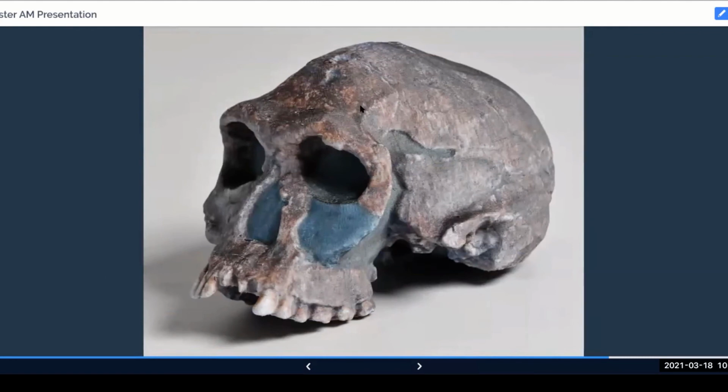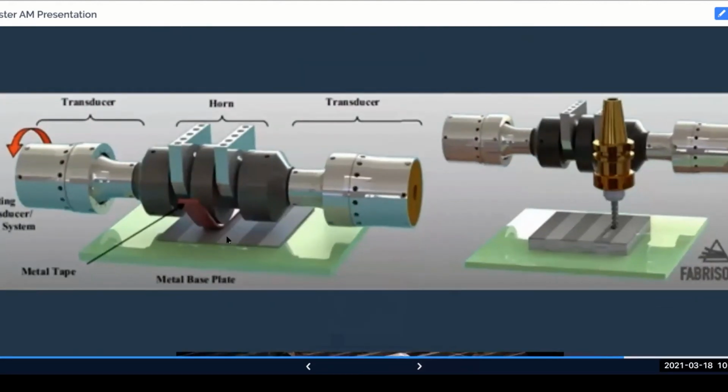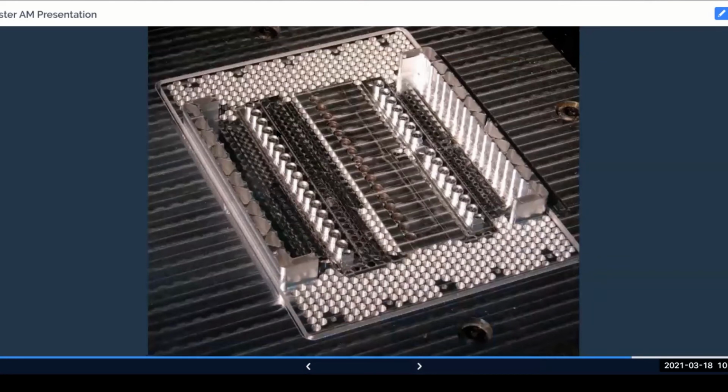So, in archaeology, they're doing this for reconstruction methods, things you want to put in a museum that looks good, like an original artifact, but isn't actually an original artifact. You can do that with this technology. So again, this is all 3D printed based on a 3D color scan of the actual part. You can do this with metal by taking little thin metal sheets and ultrasonically welding them down to a metal sheet below, and then coming back with a CNC mill at each layer and cleaning up your profile and internal geometry. And NASA actually uses this a lot for satellite technology, because the part strength of these is incredibly good. It's almost like a wrought material. So their layer strength is really strong because it's a welding process, and they can make really lightweight, very complex parts with this process because they can make them hollow.